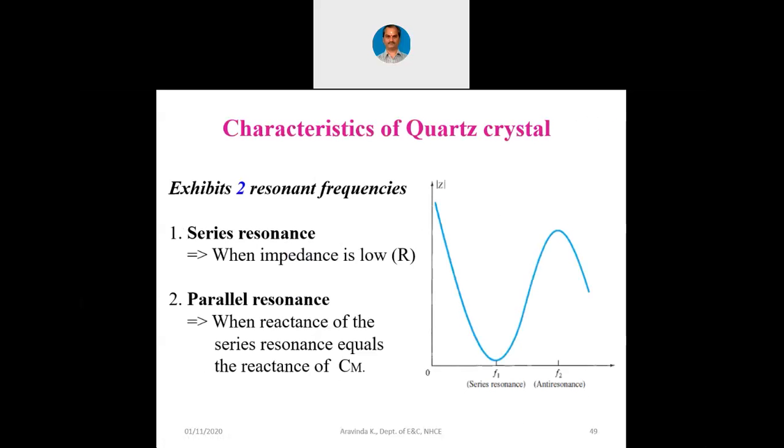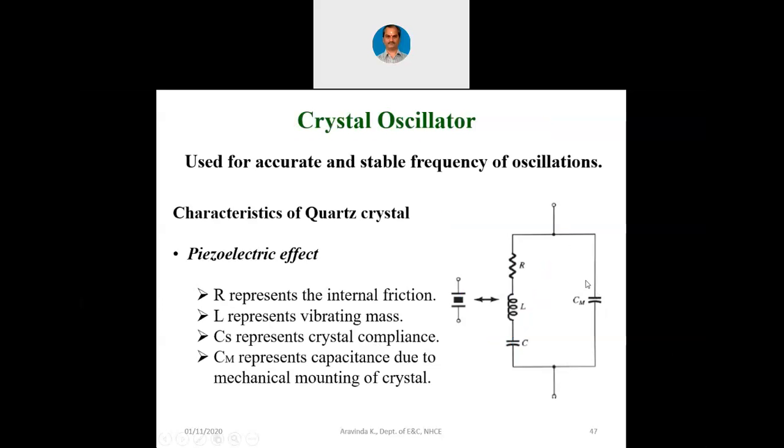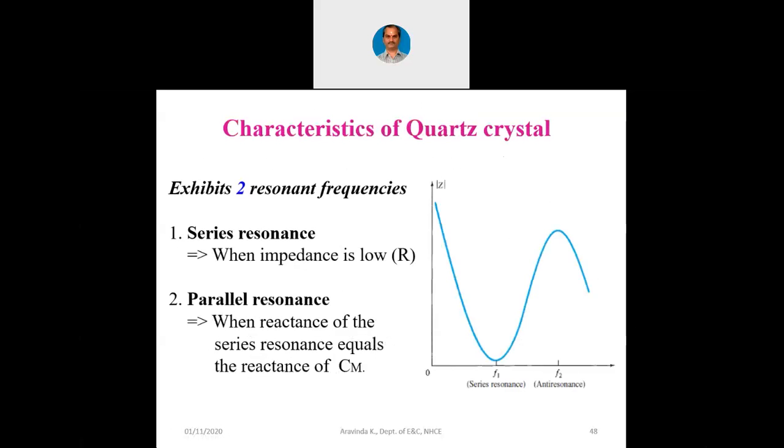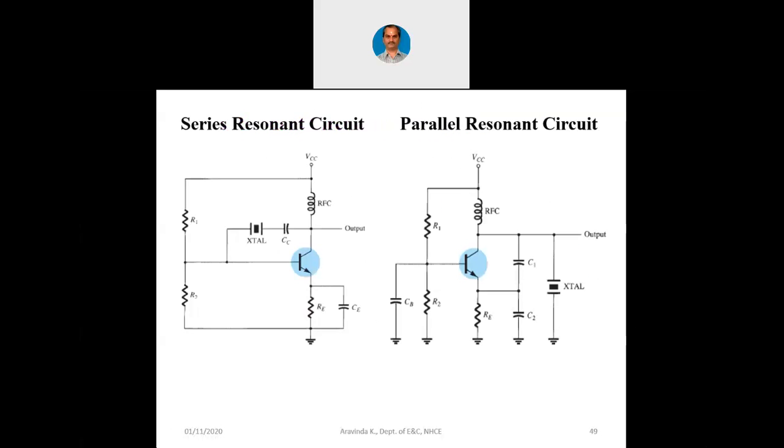That is again part of your circuit analysis. Now when the crystal starts vibrating, we can say in this manner it is in series. Even though in the equivalent circuit both are in parallel, when resonance happens, both are in series. So the effective capacitance CP is actually the parallel combination. So that way we have these two formulae.